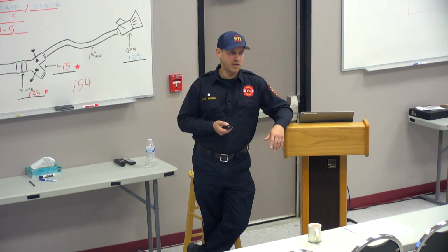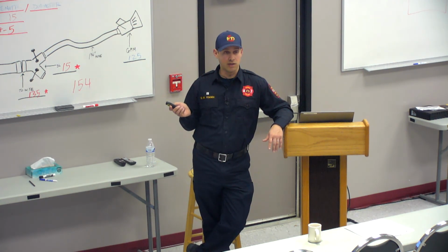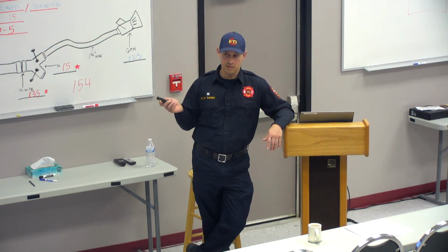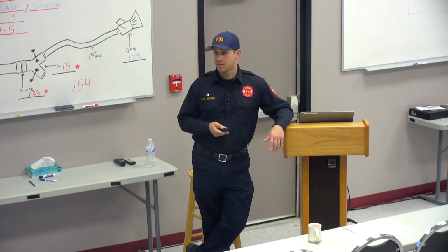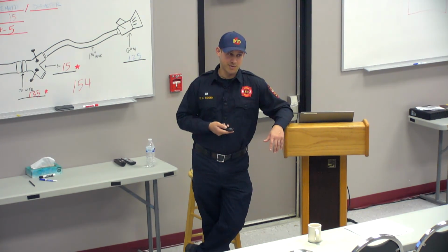I'm not saying the cavitating the pumps is wrong. This should be the number one concern. This is why we don't go below 20. Now, if you're ordered by incident command to go below 20, I'll leave that between you and incident command. I would have a comfort level with telling anybody why I'm not going below 20. Fair enough? Does everybody understand that theory? Did I mess that up? Pretty spot on? You're the expert there.